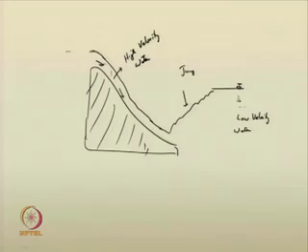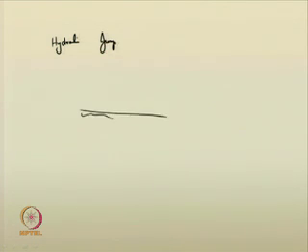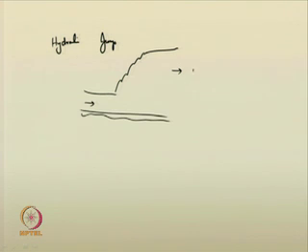So, this also causes a hydraulic jump. So, properties associated with hydraulic jump. So, hydraulic jump, if you look at it practically or in a simple, layman's form, you know that upstream the water is coming with a high velocity, and downstream water is going with a low velocity. That is the general form of hydraulic jump.